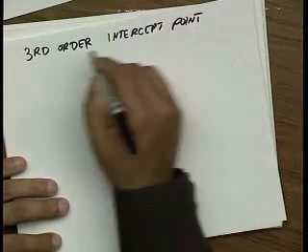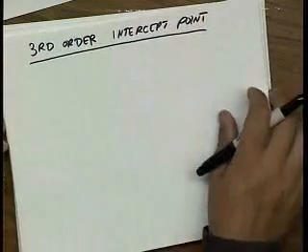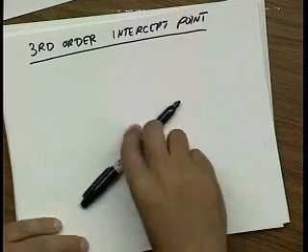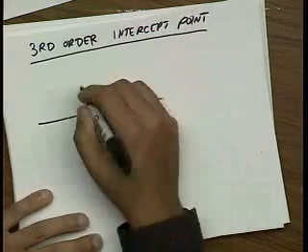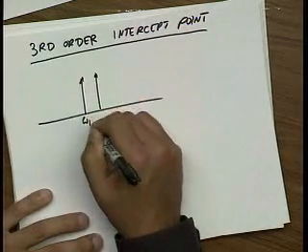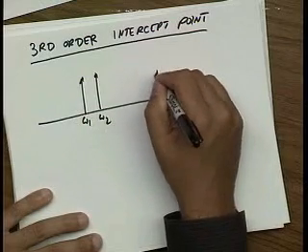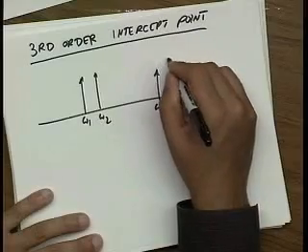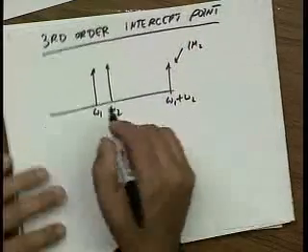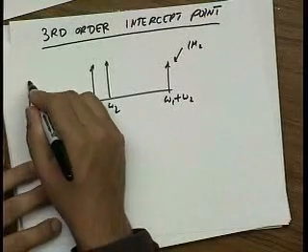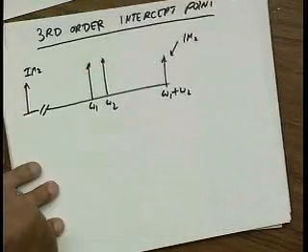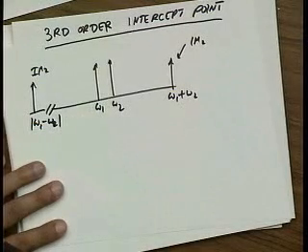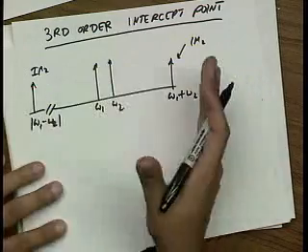Remember last lecture we talked about second order intermodulation falls at low frequency and at roughly twice the frequency if you have two tones, right? So if you have tone omega 1 and omega 2, then we had an omega 1 plus omega 2. That was an IM2 product. And then we have another term, which is also an IM2 product at frequency omega 1 minus omega 2.